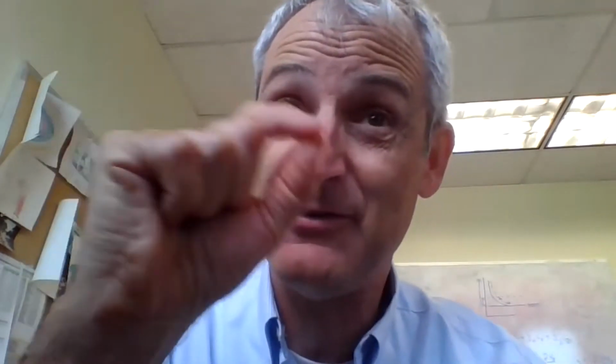I can't think of it off the top of my head, but we can model it in the sense that if you have a higher viscosity fluid, you're going to have less invasion to begin with for the same pressure drop. So you're like, oh, that's better. You get less length of invasion. But then the imbibition is going to be a lot slower for it to clear, because you're going to have a higher viscosity.